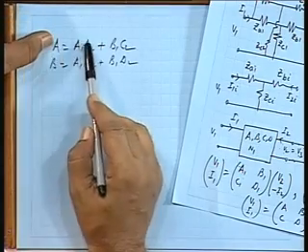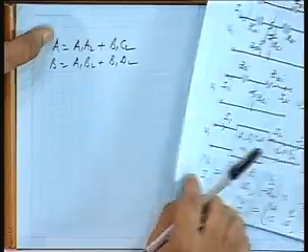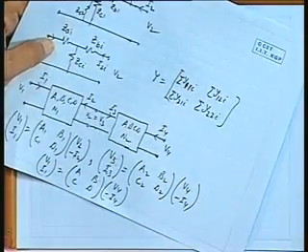Does it have a magnitude? Does it have an angle? It may have an angle. If the impedances are complex, normally in a transmission line you have RLC, so impedances are in complex form. So the ratio can be a complex constant, dimensionless, but it may have an angle. Here also it is the product of two dimensionless quantities. What was the dimension of B1?